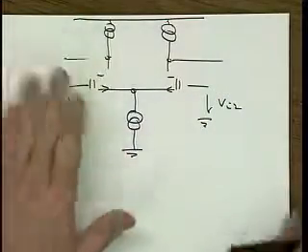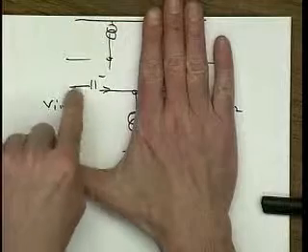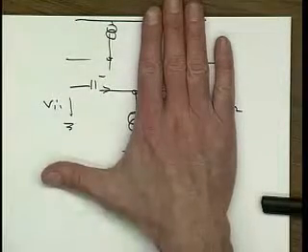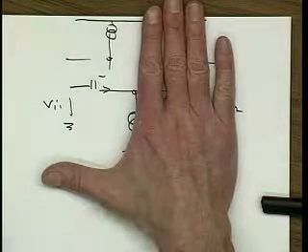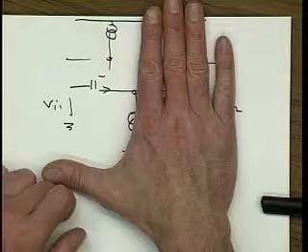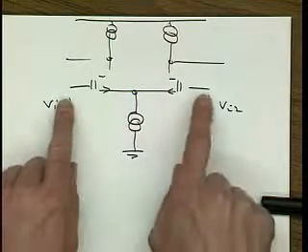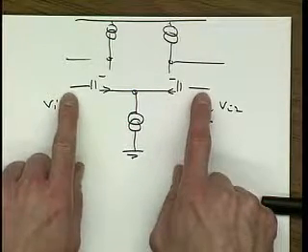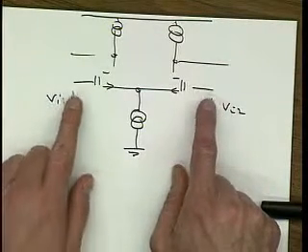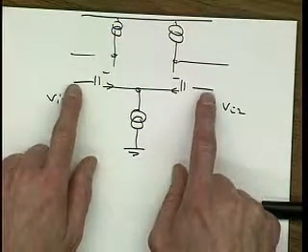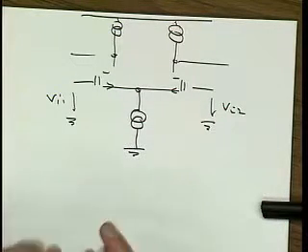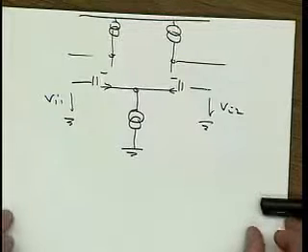So if we just have a common source stage, then we always had this biasing headache, these fancy but kind of stupid circuits that I showed on several slides, and how to figure out the right voltage we stick in. That problem we completely get rid of if we have a differential input. Then this voltage here and the voltage here is still a bizarre thing, but what the amplifier amplifies is the difference between these two, and so the value of the threshold voltage, for example, just drops out in this difference.